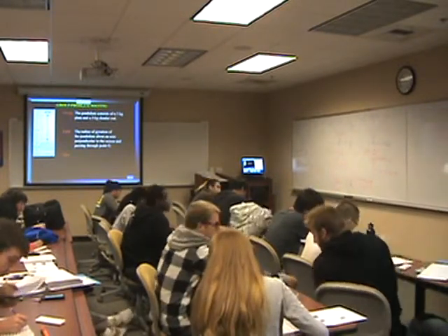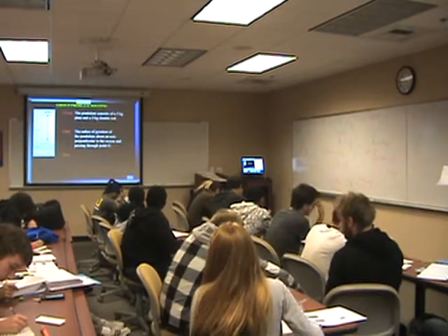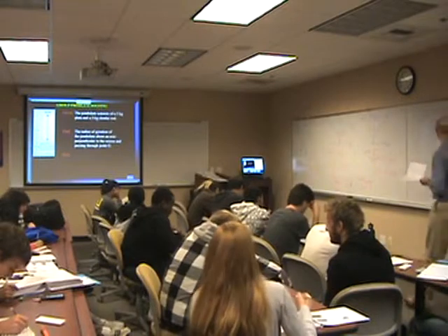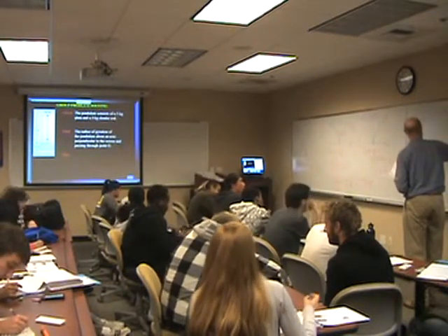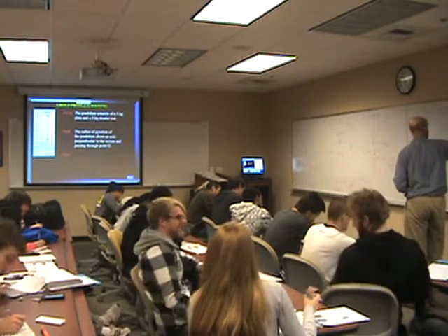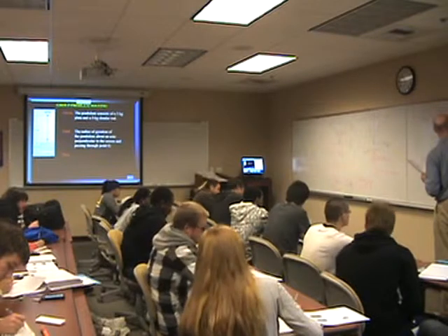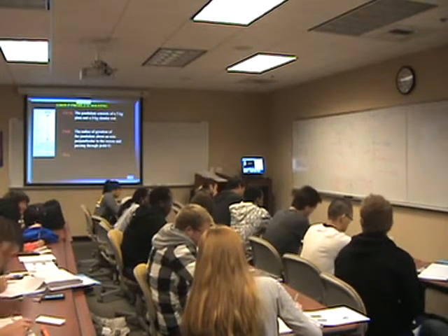It's 2 for the rod plus another half to get to the center of the plate, and we divide all of this by 3 kg plus 5 kg, the sum of the masses. This is 1.781 meters.